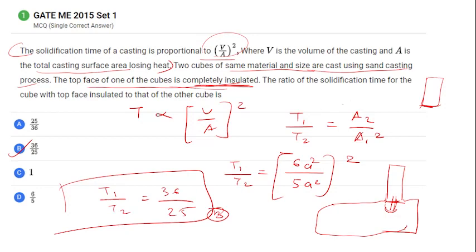See, firstly, riser is connected with the metal casting, right? They both are connected. So when you're designing it, you're designing in such a way that the casting will be solidified first and the riser will be solidified last, right? After this will be solidified. So if you're taking its solidification into consideration, after solidification of your casting, the riser started solidifying, right? So this is already solidifying, so this surface will also lose the heat, right? Now it is not working as a heating chamber, right? So this will also lose heat now, so you will consider this part also. You understood my point?